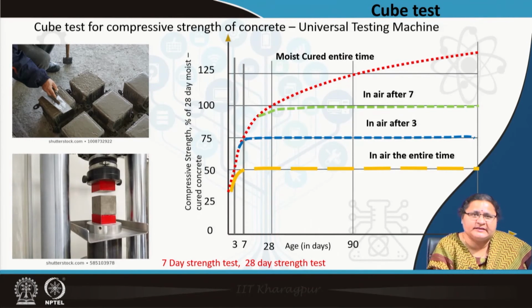So, remember, when you are making these cubes, proper tamping should be done because voids can mislead you, and hence these are to be done very carefully, and the tests are to be done exactly on the same days.